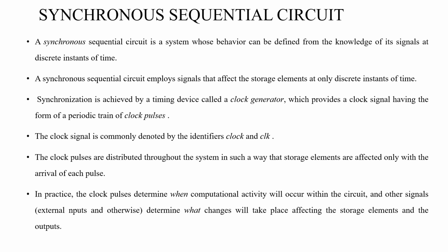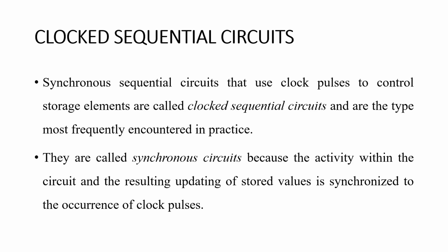A synchronous sequential circuit is a system whose behavior is known from its signals at discrete instants of time. A clock signal is commonly denoted by the identifier clock. The clock pulses are distributed throughout the system. The storage elements are affected only with the arrival of each clock pulse. Clocked sequential circuits are used to control the storage elements and are the type most frequently used in practice. The sequential circuit changes the stored value on the occurrence of the clock pulses.